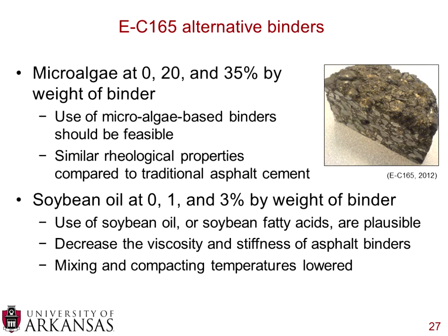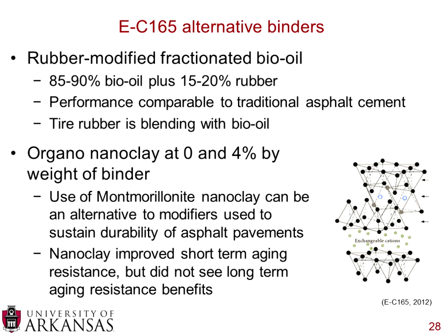And this is a very nice finding because we're always trying to figure out ways to reduce energy consumption. We're trying to figure out ways to increase haul distances and keep that mix workable at the lower mixing and compacting temperatures. So this could potentially be a warm mix additive here if we are able to reduce those mixing and compacting temperatures while maintaining the proper performance we're expecting out of asphalt concrete.